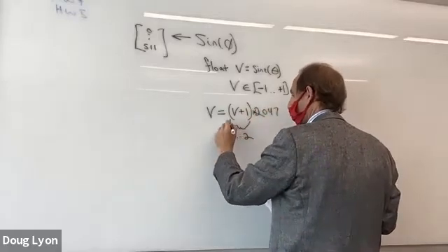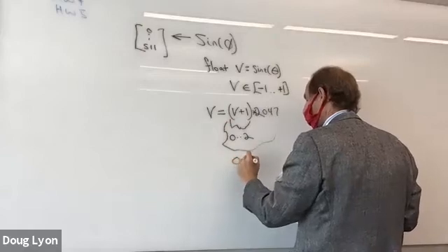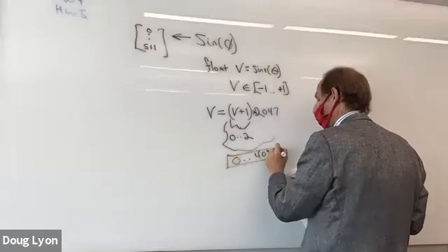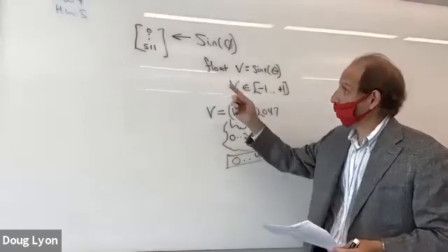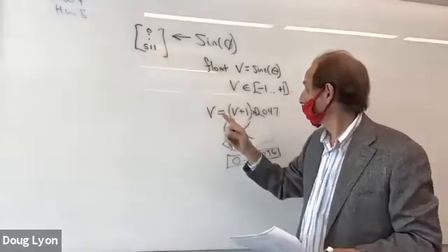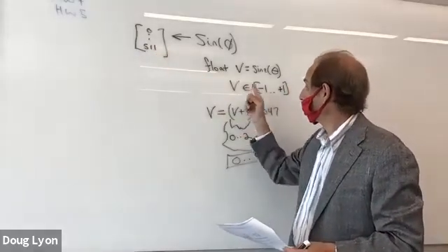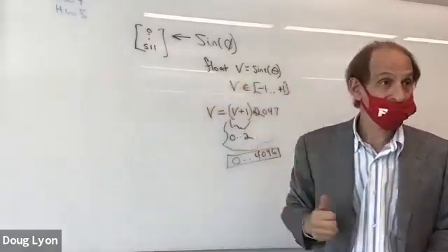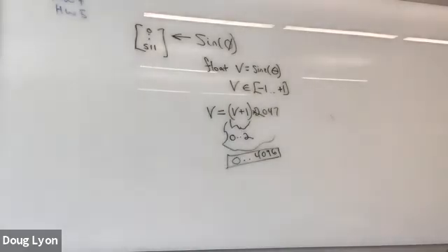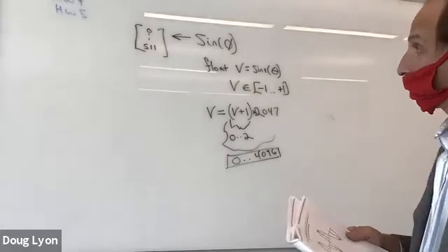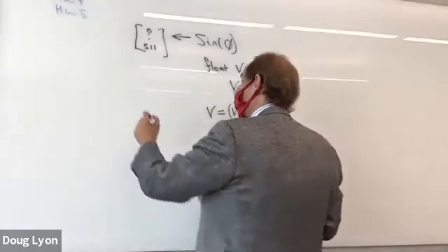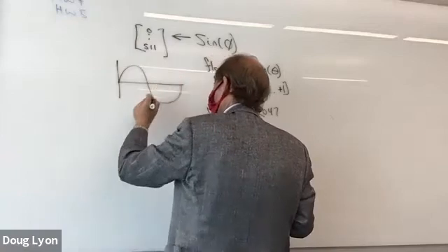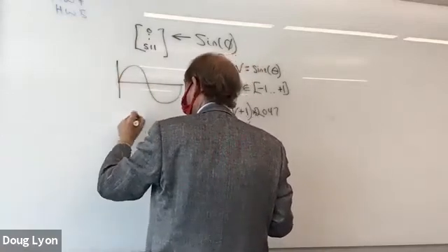And now I have something that ranges from 0 to 4096. That conditions the output so that A, it can be put into this array, and B, I don't have to do any scaling before I pump the numbers out to my digital to analog converter. So I'm going to take this 512 sampled sine wave, this high precision 16-bit sampled sine wave with 512 samples.